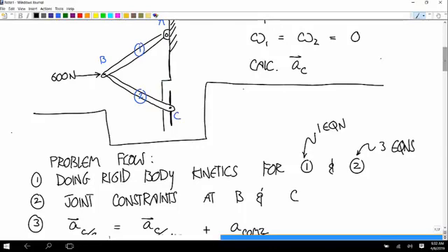This joint, because it's a tangent slot joint, restricted motion along the x-axis. And so we're going to have one more constraint equation that just says the acceleration of this point C has to be 0 in the x component. Okay? The x component of that has to be 0. But along with that extra constraint came the force that enforces that constraint, which is the normal force saying you can't go horizontally. Okay. So that's why you always have the same number of variables that you have equations after the constraints.